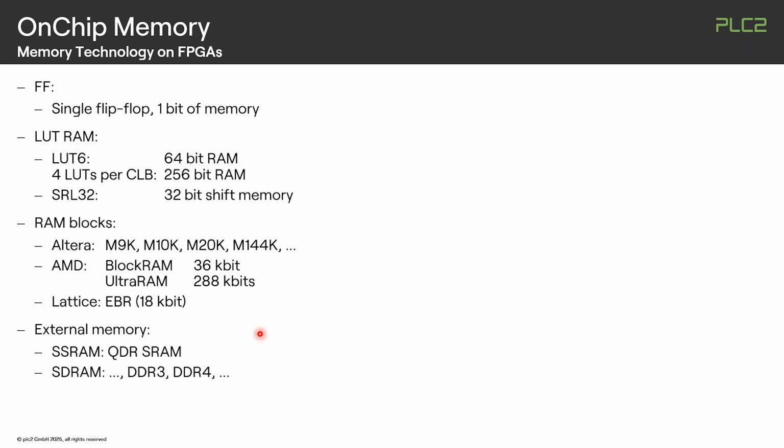Then another memory technique that is available is external memory. It's maybe not in the scope of this presentation. Just for completeness, we can have static and dynamic external RAMs like QDR SRAMs or DDR SDRAMs. This is possible. Maybe at a later stage, we can give you a presentation about a memory controller like a FIFO that is using external memory. So in case you need very big FIFOs not fitting into the BlockRAMs, we also have a solution for it. This is currently an internal IP to PLC2, and maybe in a year or 2 we can discuss this technique.